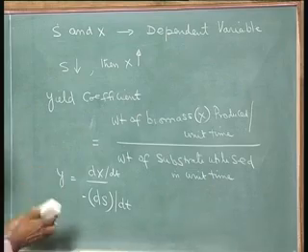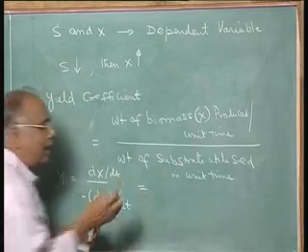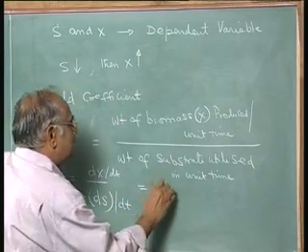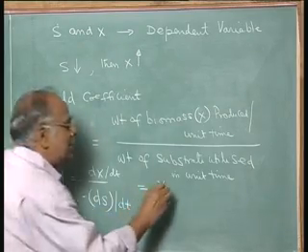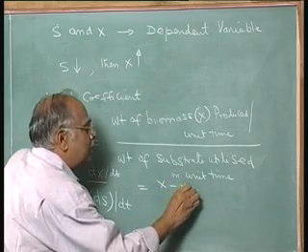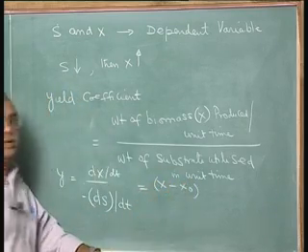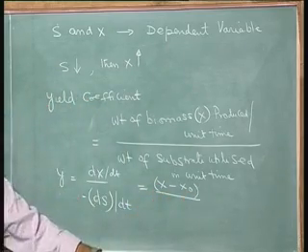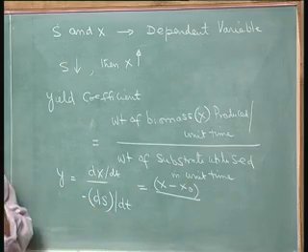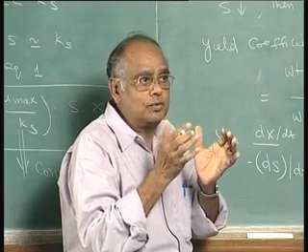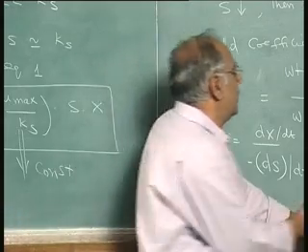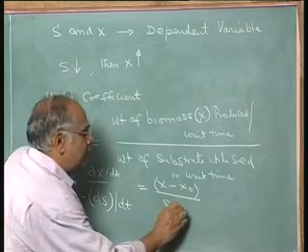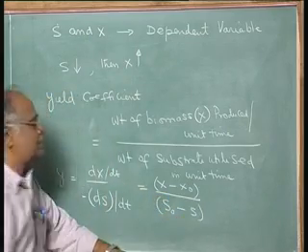So now this particular equation can also be written in finite terms of time. Suppose I take a finite time, X is the concentration of microorganisms at any time minus X naught, that is the initial value, divided by the utilization of substrate concentration, initial substrate concentration is S naught, that is at time t equal to 0, minus S. So this is the expression we have.